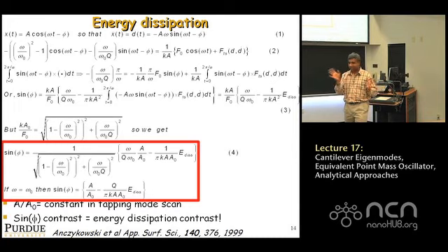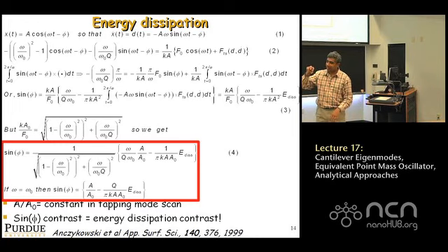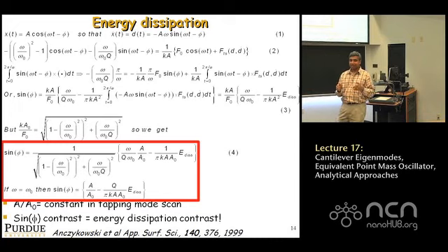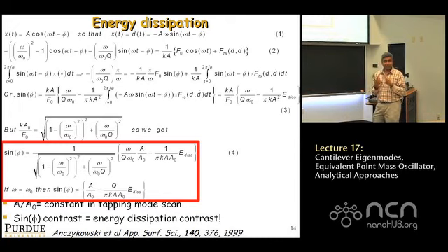Right? So all of us know how to measure energy. We take a ball, let it go, it bounces, it doesn't go back to the same height. You've lost energy in the impact, right? That's with the tennis ball, let's say. This is the smallest mechanical ball that it's tapping, moving away, and you measure the loss due to the interaction between a few hundred atoms and a few hundred atoms on the sample. It's amazing if you think about it. All right? That's the E_dis, energy lost to the sample in one cycle of oscillation.